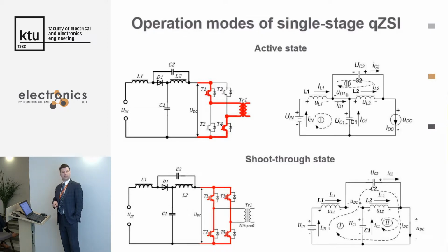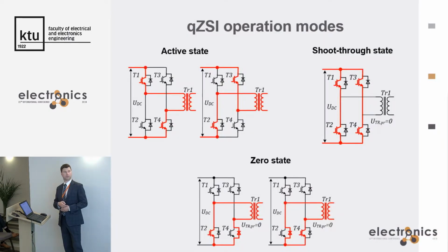by storing magnetic energy, which in turn provides voltage boost on the primary winding of the transformer, and we can increase input voltage. So that's how we can keep stable DC link voltage. And besides that, this inverter works as a synchroinverter and mimics a synchronous generator in the grid.